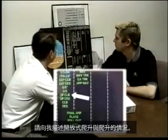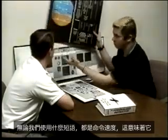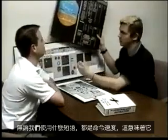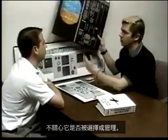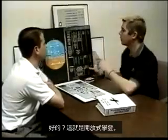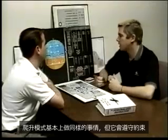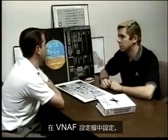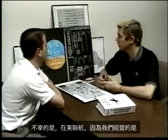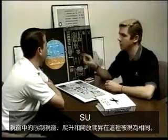Describe to me open climb versus climb. Okay, open climb means to climb at a speed. A phrase that we use is a commanded speed, which means it doesn't care if it's selected or managed. It's going to climb at whatever speed I have set here. Okay, that's open climb. Climb mode does basically the same thing, but it'll obey the constraints that are set in the VNAV profile. Unfortunately, at United, because we operate with the most restricted window in the SU window, climb and open climb are treated the same here.